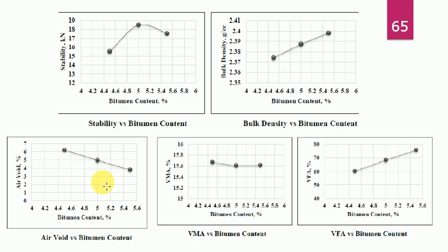Then at that bitumen content you have to check the flow value, the VMA value and the VFA value. So this is the overall procedure for the Marshall mix design.